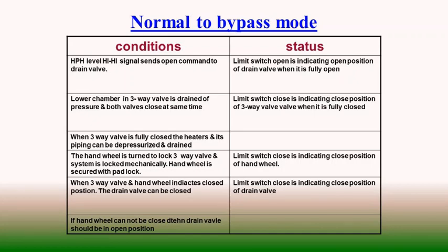Now we find all these heaters which are attached to this regenerative feed water heating system, most of them are connected with uncontrolled steam flow, extraction steam flow. Some are connected with NRV arrangement, and some are connected with some globe valves or isolating valves. But the thing is that the level of extraction, the amount of feed water flow through these extracted steam heaters, naturally it affects the functioning.